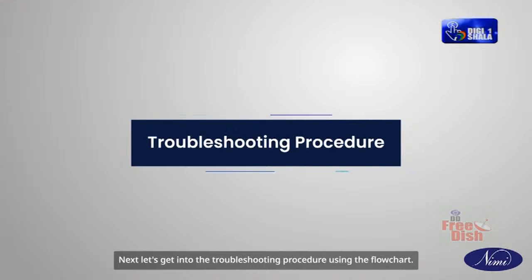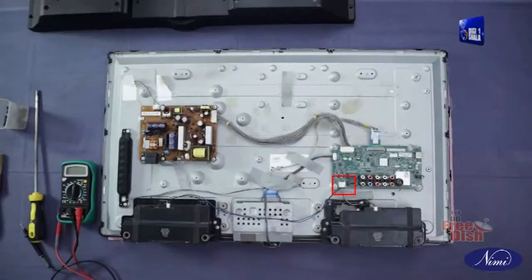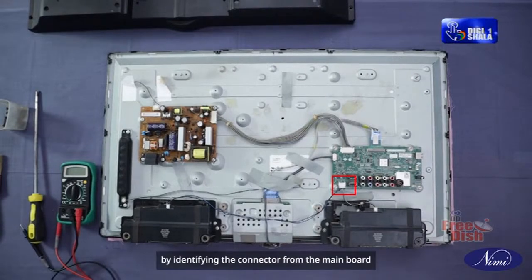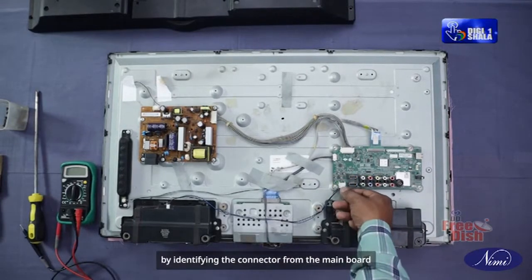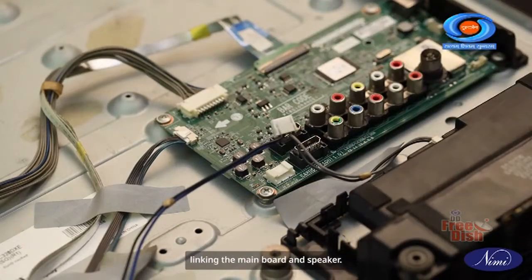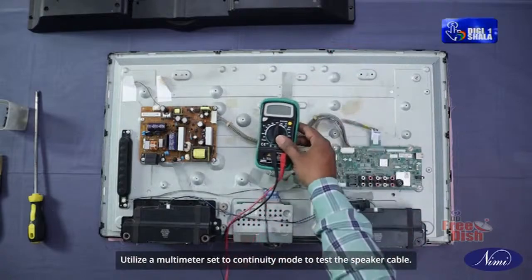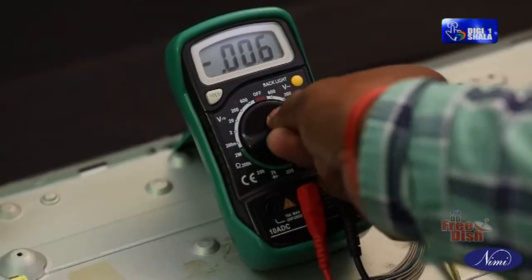Next, let's get into the troubleshooting procedure using the flowchart. To perform the cable and speaker test, refer to the provided flowchart. Begin the speaker cable test by identifying the connector from the mainboard and carefully disconnecting the cable linking the mainboard and speaker. Utilize a multimeter set to continuity mode to test the speaker cable.